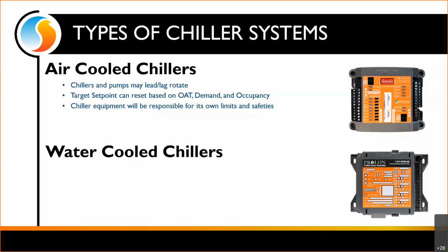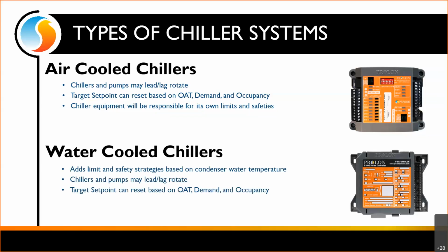When we move into water-cooled chillers, though, it is a little bit different, because a water-cooled chiller is usually a component of a much bigger system. It has really an unrelated, separately controlled cooling tower going on with it. And there's the possibility that something could happen in that cooling tower, a failure or whatnot, that the chiller is not aware of.